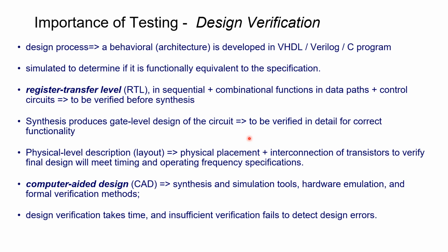So design verification takes time. Typically 70% of the life cycle is verification. It can fail to detect design errors, and any amount of verification is not sufficient. The verification manager or the director controls the tape out. So verification is an extremely key thing. How do you know you have verified it thoroughly? You'll see in the next semester course, in SystemVerilog and verification. About 70% of your overall effort to tape out goes into verification.